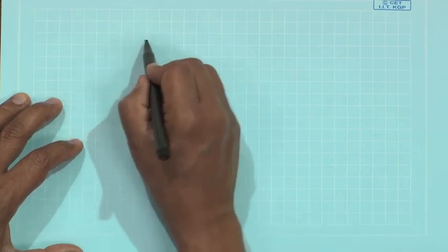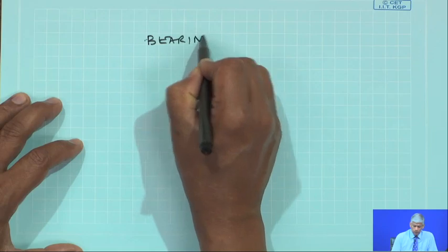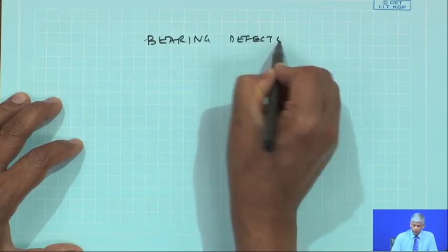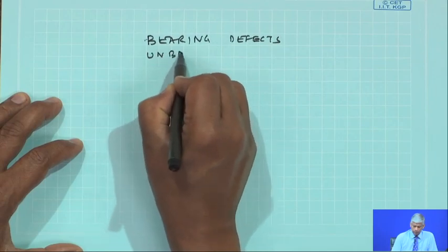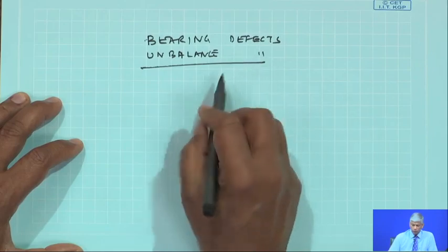But out of my practical experience, I must tell you that whenever we have a machinery with misalignment, if this was neglected, it sometimes becomes difficult to identify because of bearing defects, because of unbalance, etc., and so on. So, one has to keep that in mind.